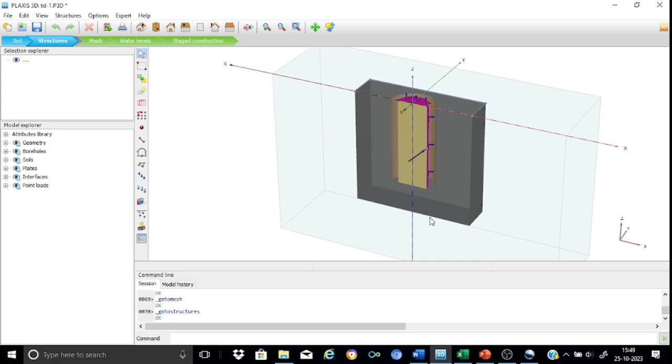This is to ensure that we perform an accurate calculation of the capacity of the suction anchor by refining the mesh sizes very near to the suction anchor. This zone can be easily created. You first create 3 lines of the top surface, extrude till the bottom surface, and then create an additional bottom surface. That's all. Now let us proceed over to the mesh.